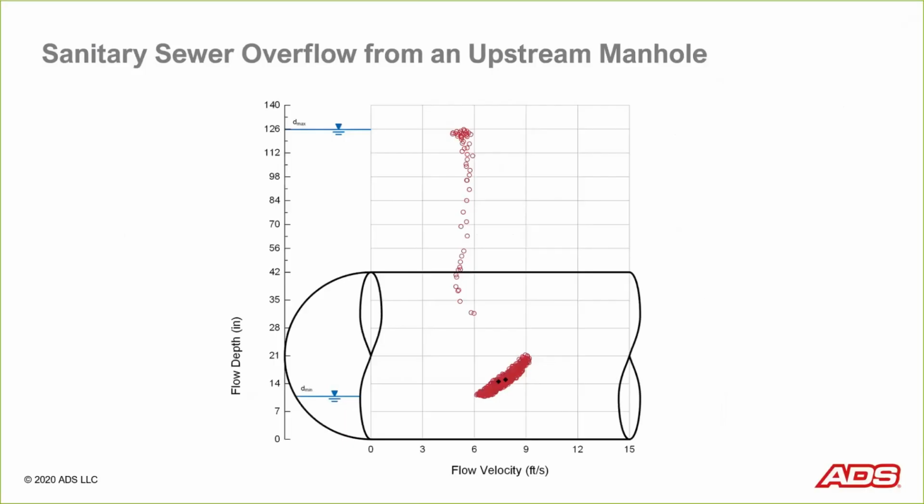So here's data from a 42-inch diameter sewer. This one happens to be in Maryland. And again, by now you should already recognize that this location has uniform flow, backwater, and surcharge conditions in it. And we've learned today that those are the prelude conditions to an SSO.